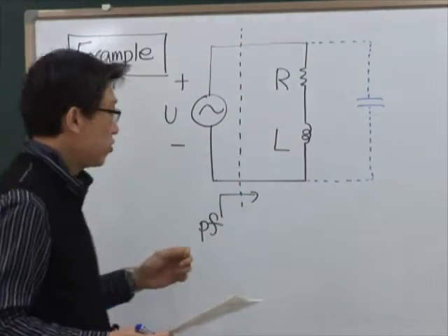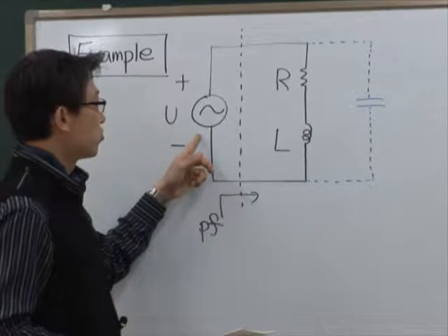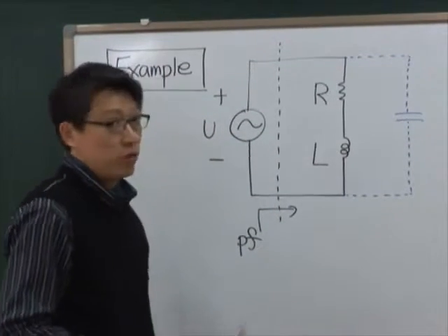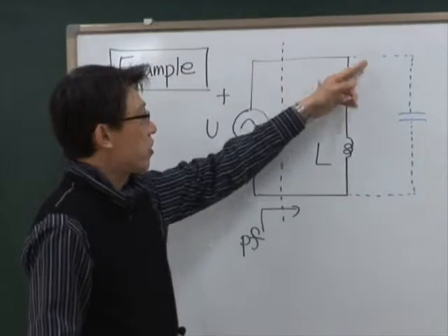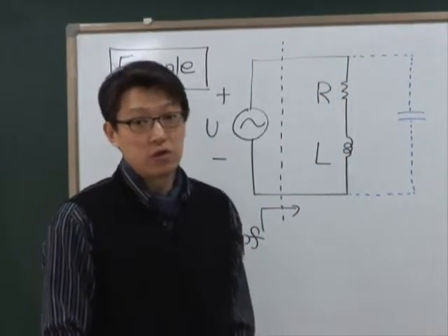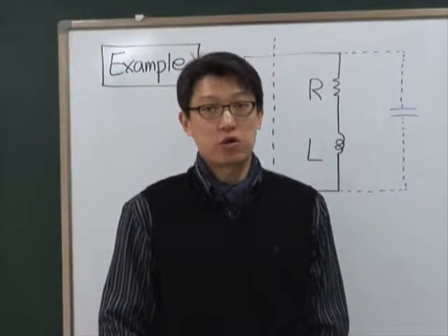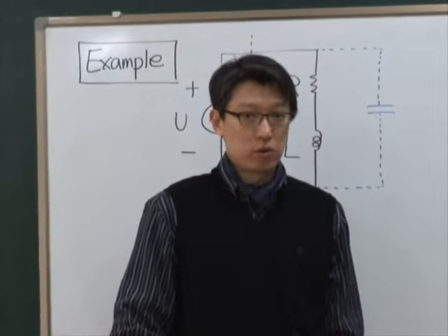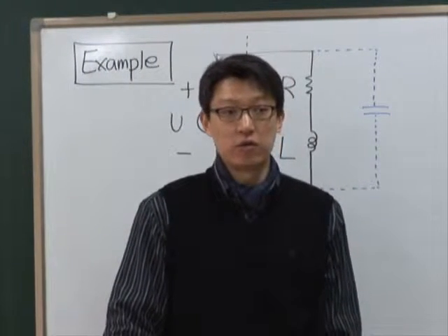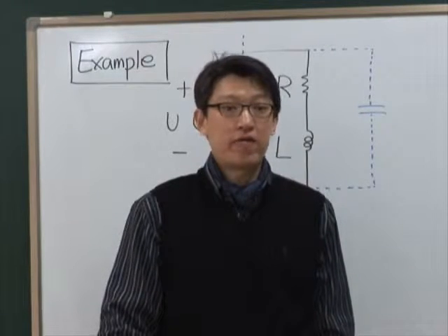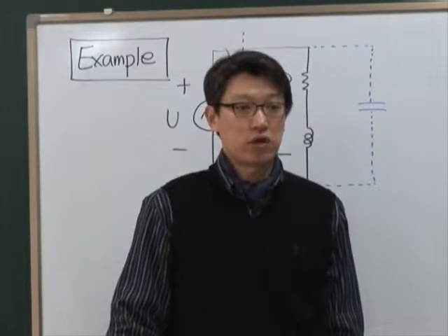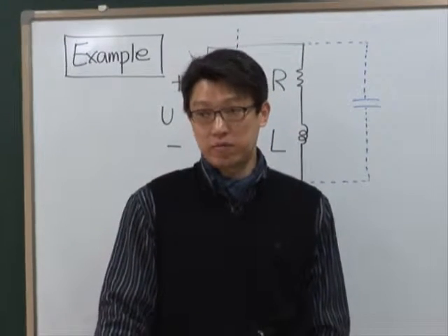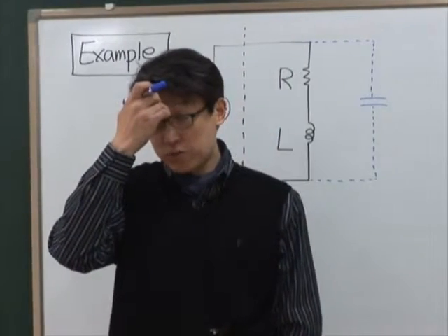So we start with this AC sinusoidal voltage source and resistor and inductor. You can think about this as a factory, R and L. And usually the factory is equipped with a lot of motor loads. The factory has a lot of motors, and motors, as you know, are an inductive load, RL. So the power factor is very low, sometimes approaching 0.5 lagging. So the utility company now asks factory people to upgrade or increase the power factor.